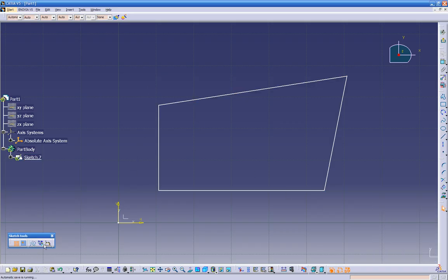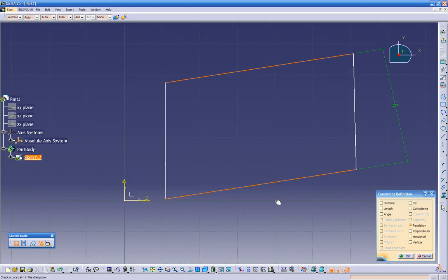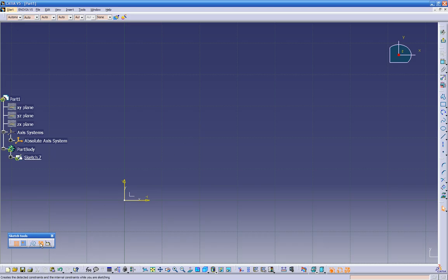And let's activate this option, the geometrical constraint. And let's try it again. Pre-select the line with this line. Let's go back to the constraint. And watch this, we're not going to get the alarm anymore. See, because we constrained it. So let's cancel this. Let's delete this rectangular. Let's try it again with this option already highlighted. And the same thing with the dimensional constraint.